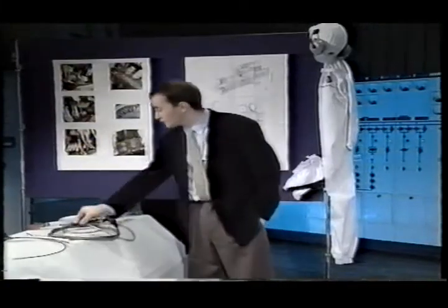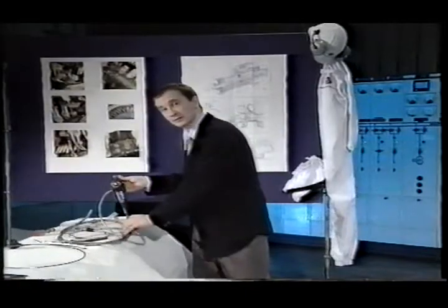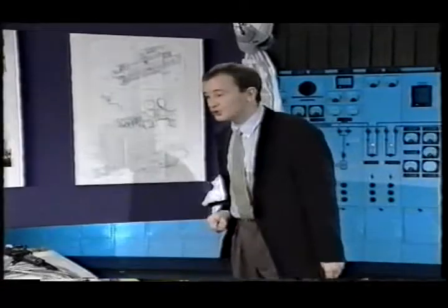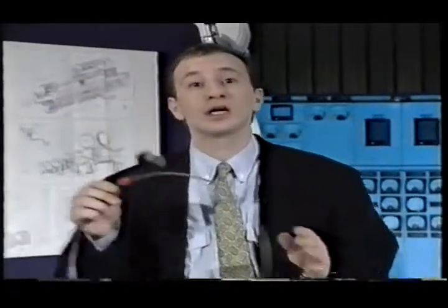Some hours later, the object of the search was found. And here it is, a 6-inch long Allen key. It was found with the aid of an intrascope inside the rotor fan. It was retrieved using a magnet attached to a curved rod. Fortunately, in this particular case, the fitter working on the job had the presence of mind to declare the fact that he had lost a tool, and the supervisor, despite pressure to get on with the job, insisted that the fullest search was carried out. But things don't always turn out as well.